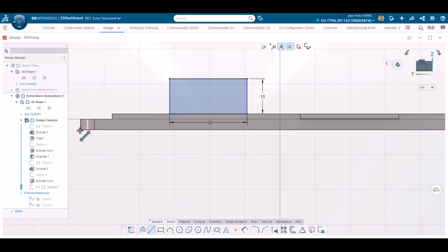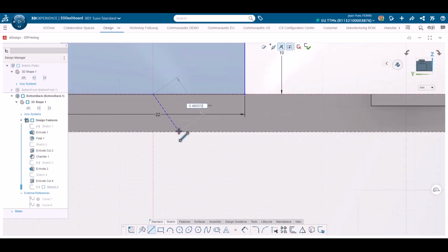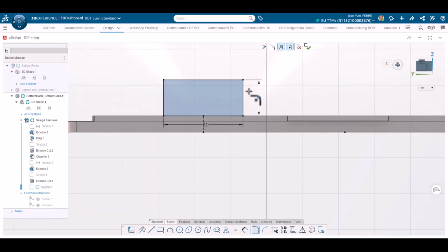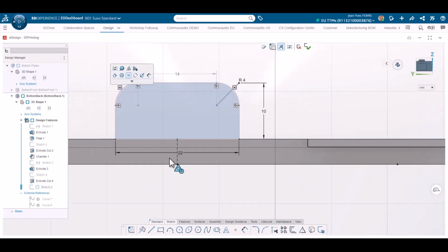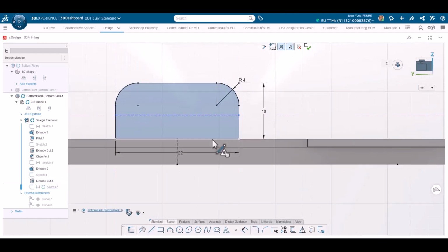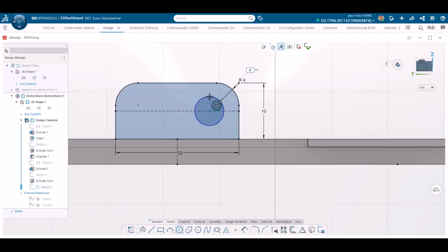I will finish the design with some strong fastening solutions. Two bosses with two screws each. This time the bottom parts will not move at all. So I create the first boss. Of course I forgot again to deactivate reference geometry when adding fillets, so I have to revert back to plain arcs.